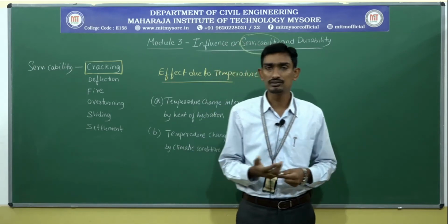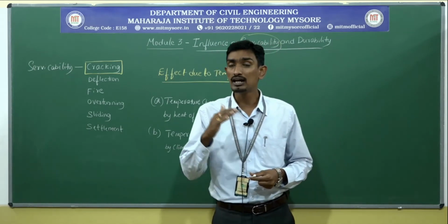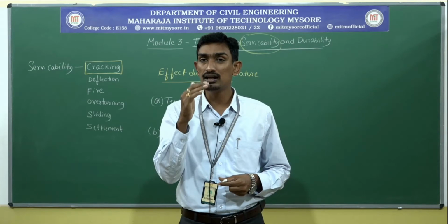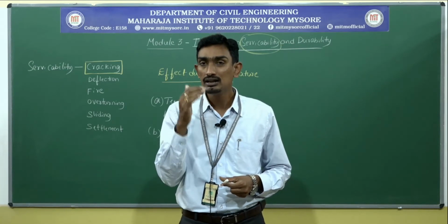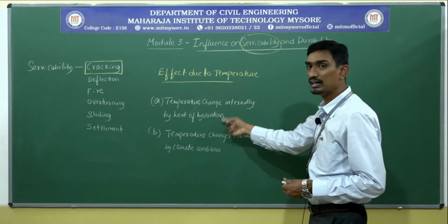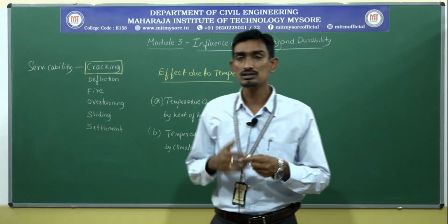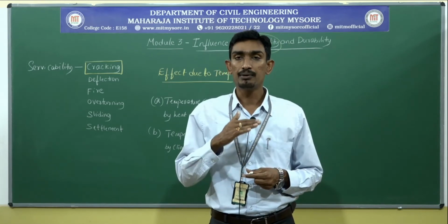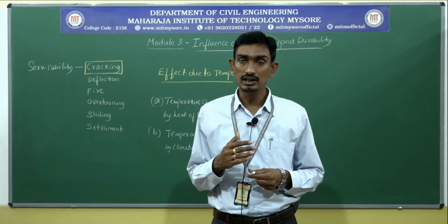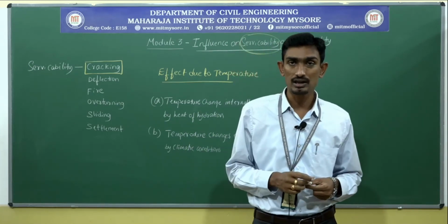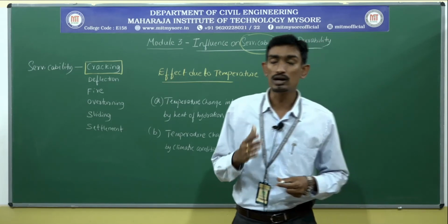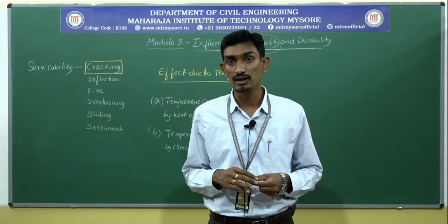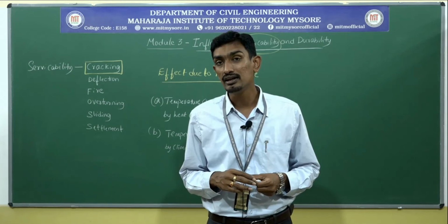Okay, because of this, the temperature will also rise. Why? This temperature will be raised internally due to heat of hydration. Because of the exothermic reaction, or because of liberation of heat, the temperature rises. This rise in temperature will reach about 38 degrees centigrade.